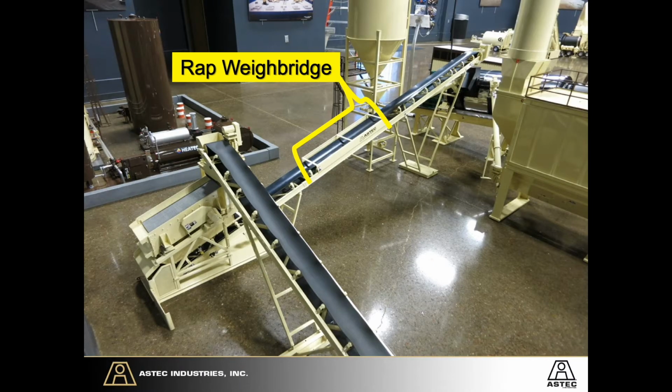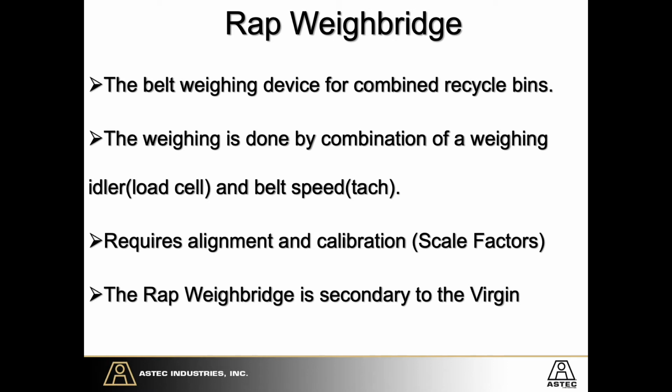As far as the conveying system, you still have a wrap weighbridge. That wrap weighbridge is going to follow the virgin weighbridge. It is the combined weighing for all of the recycle bins. It also has to have the combination of weight and speed, so you've got a weighing idler or a load cell, and you also have a belt speed tach or an encoder.